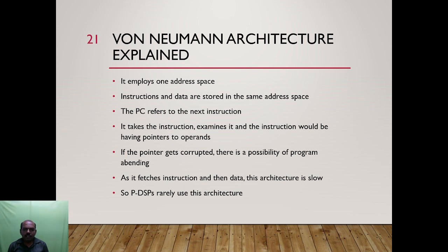The PC refers to the next instruction. It takes the instruction and examines it, and the instruction would have pointers to operands. If the pointer gets corrupted, there is a possibility of the program being abandoned, as it fetches the instruction and then data. This architecture is slow, so programmable digital signal processors rarely use this architecture.